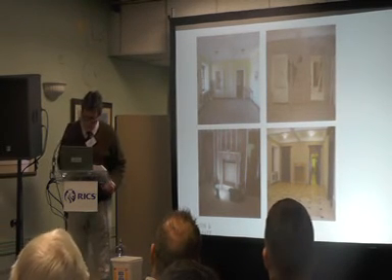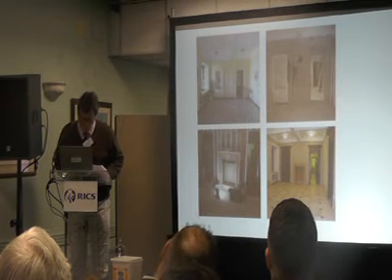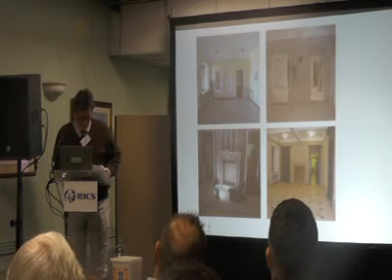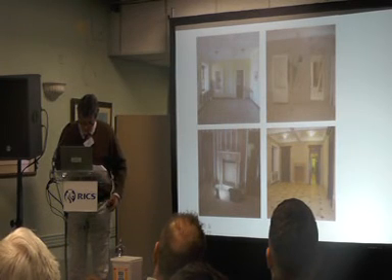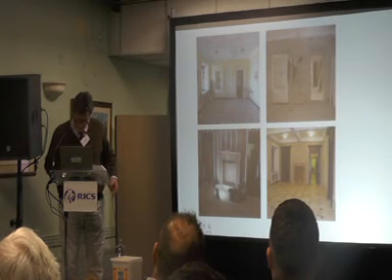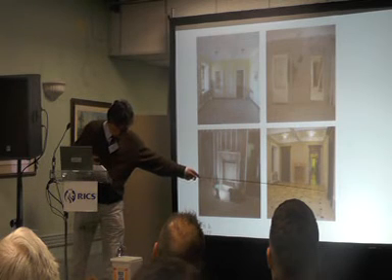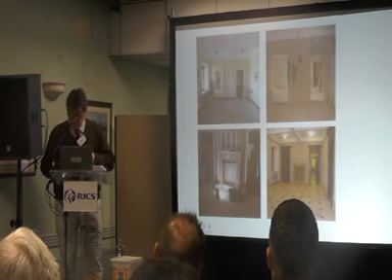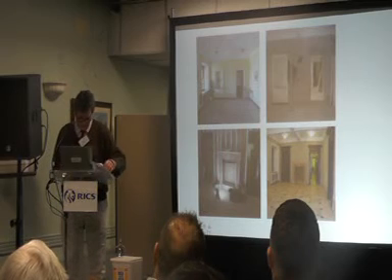We actually found Lorimer's original drawings before starting the work, and we knew that he planned beautiful pedimented doors, and we brought one of his own fireplaces from a Georgian room where it shouldn't have been down into this hall. The bottom right picture is of it finished. So it's been stripped, strapped, an exact replica of the plaster has been put back but dry, and there's ventilation going in behind the skirting and out at a line you can't see. It's obscured behind a little fillet. Absolutely fabulous piece of restoration work in my view.